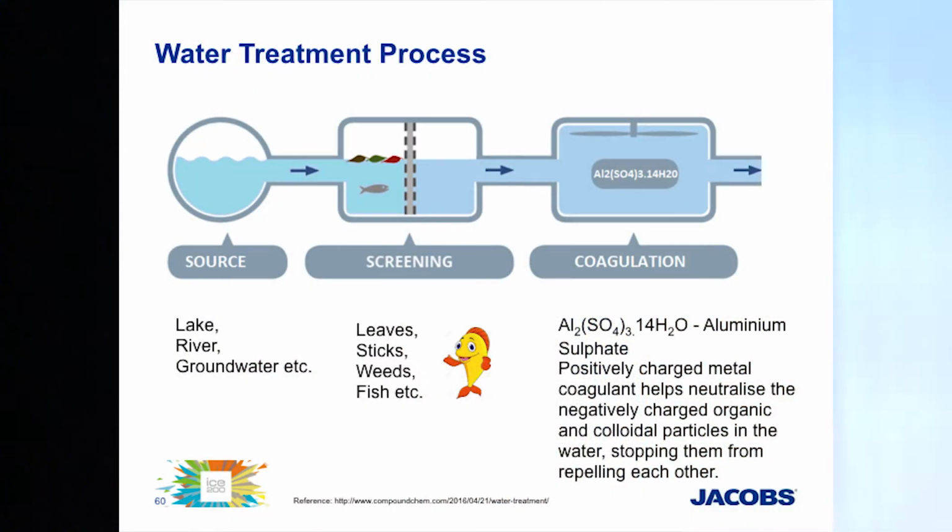So from the ground, water treatment works aren't that exciting. They're just a series of consecutive tanks, but you can't really see what's going on below the surface. So we're going to take a look at each of the processes. Your water is piped in from the source, whether it's a lake, a river, or maybe an aquifer, then passes through a screen. The screen will stop a lot of debris, leaves, sticks, weed, fish